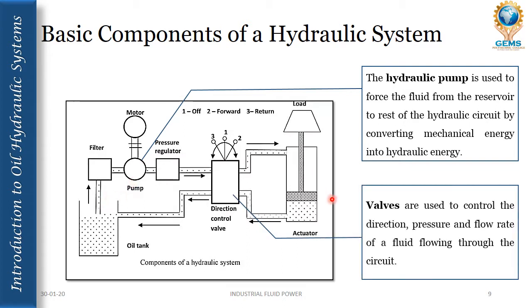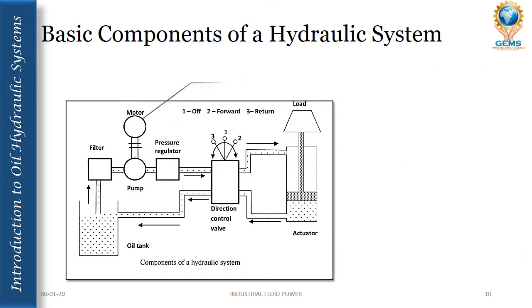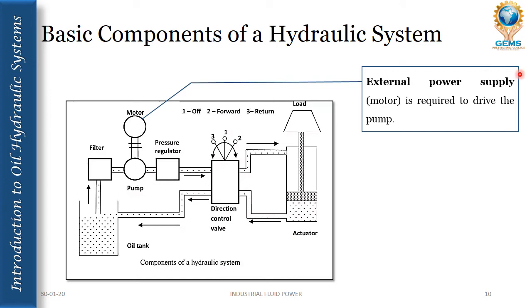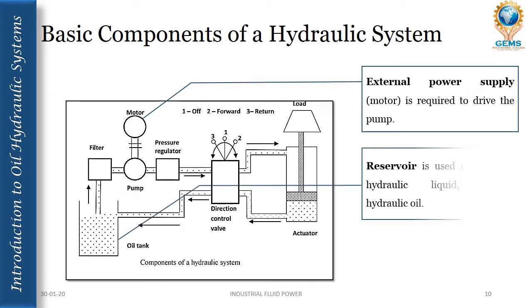Then these are the valves. The valves are used to control the direction, and some of the valves are used to control the pressure and flow rate of a fluid flowing through the circuit. And this is the external power supply, that is, a motor is required to drive the pump. And this is the reservoir or oil tank, used to hold the hydraulic liquid, usually hydraulic oil.